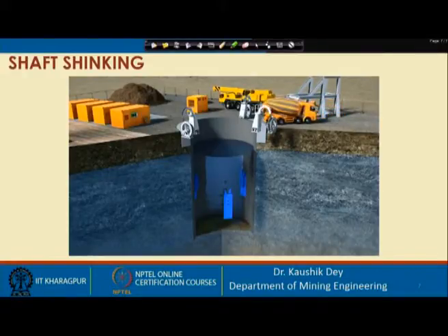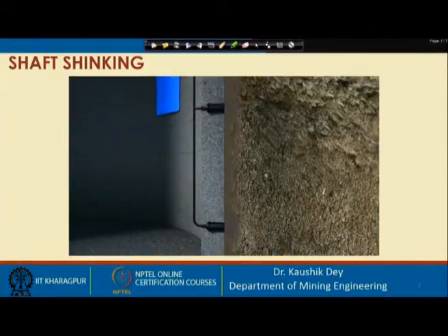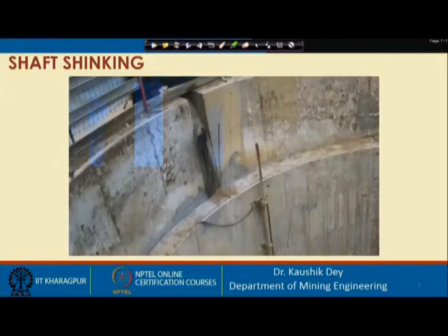After achieving the desired length, the drill rig is withdrawn, then the bottom is concreted, and the shaft is completely drained out. Afterwards, the bentonite in the annulus around the shaft is displaced by grout injected through the bentonite nozzle.